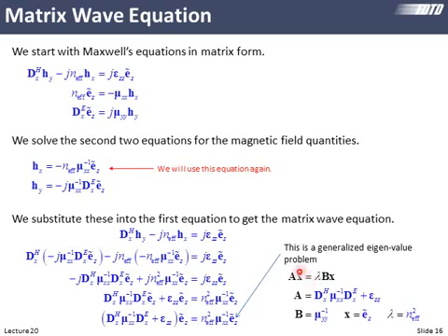So this is what the fields would look like, and this will be the effective index squared. So it's almost our propagation constant. We went through a whole bunch of stuff, and here is our generalized eigenvalue problem. So we'll extract a slice from our FDTD grid, analyze it as a slab waveguide, and then we calculate the modes by solving this generalized eigenvalue problem.